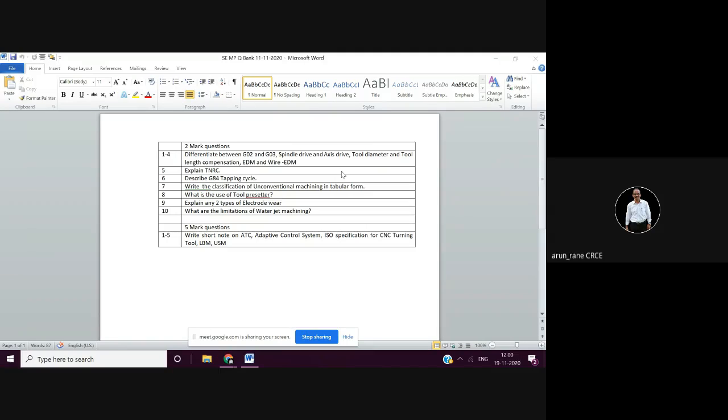So you have to take this boring bar to the presetter and then set that cutting tool, which means you have to take it in or out such that the diameter will come to 28.32. You have to put a dial indicator to the tip of the tool, and set it in such a way that the dial indicator will show 0 when the size comes to 28.32. This is what your diameter setting is.